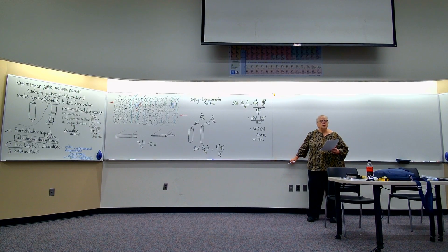Now, I'm not told the condition of this piece of copper before I started to deform it. I'm assuming there was no cold work in it. If there was, then what I'm doing is adding to that percent. So if it said this has already been cold worked 10%, then my end result here is 46% cold work. Okay?